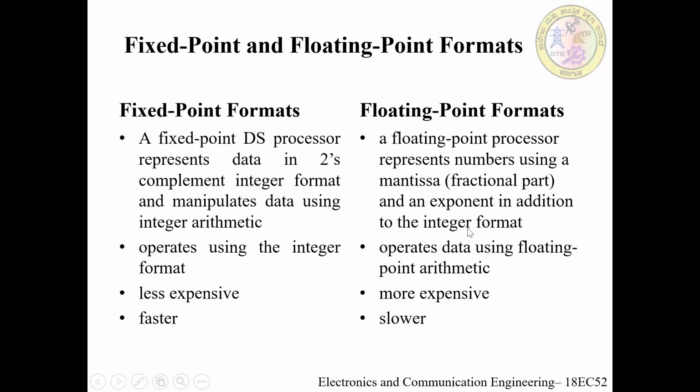However, the floating point digital signal processor contains more hardware units to handle the arithmetic. The floating point arithmetic, hence, is more expensive and slower than the fixed point processors in terms of instruction cycles. It is usually a choice for prototyping or proof of concept development.